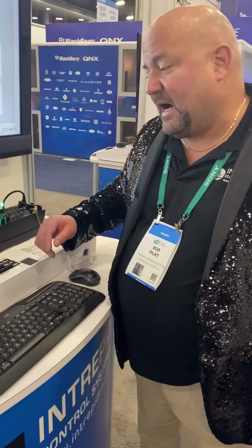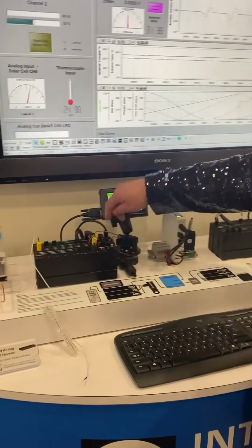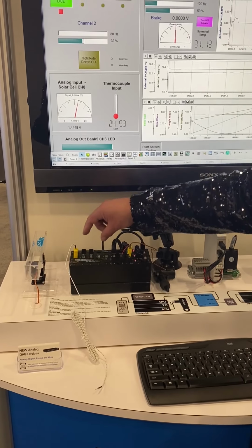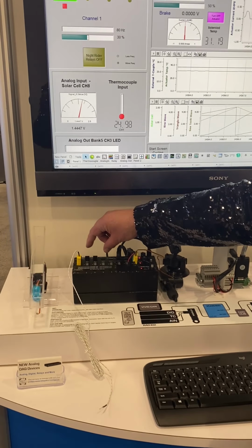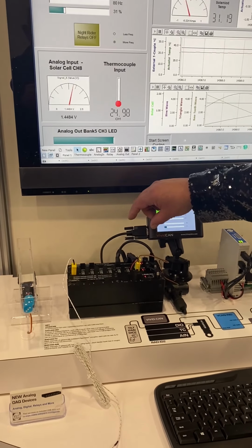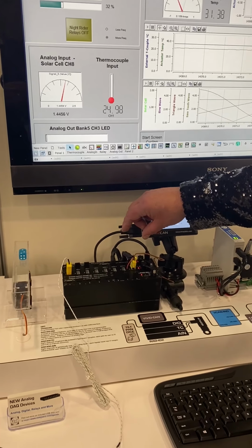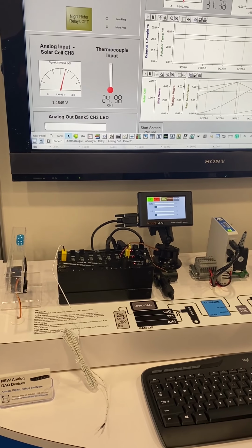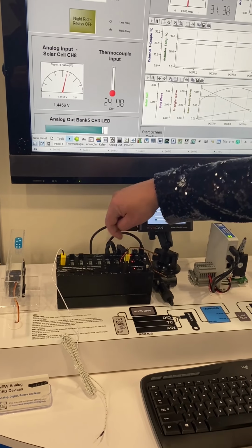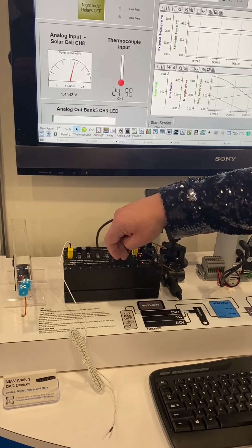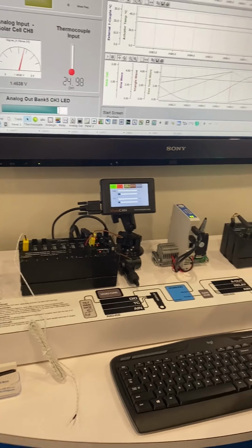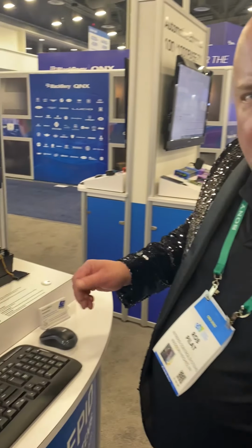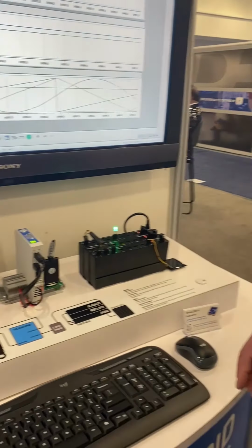Basically, a breakdown of the modules. Again, the DIO is eight banks: 4 banks of digital input, 3 inputs each, so that's 12. And there's 4 banks of output, and each bank has 2 half bridges, which can be used as a full bridge. This is K-type thermocouples, and these are analog inputs. The important thing about the RAD-IO2 is everything is galvanically isolated to at least 1500 volts, so you don't have any issues with common mode or shorting between channels.